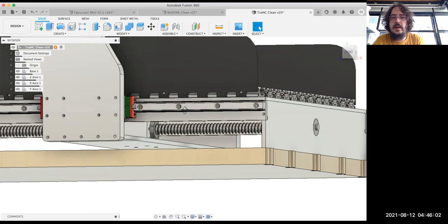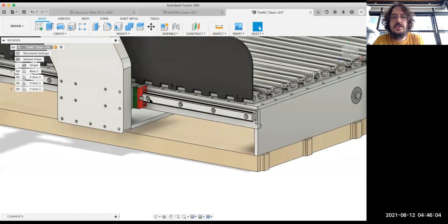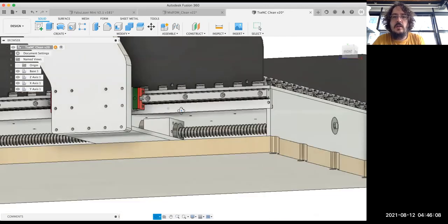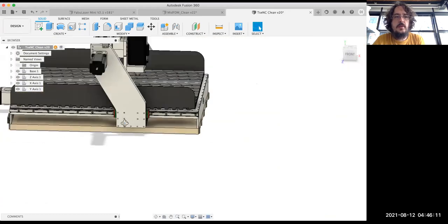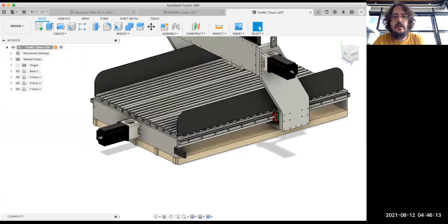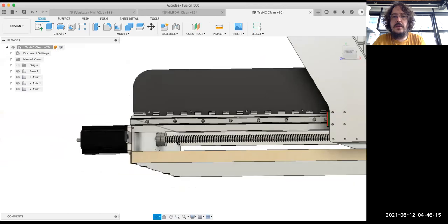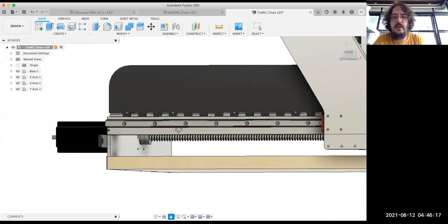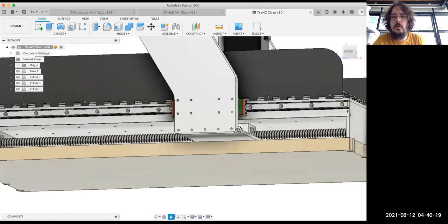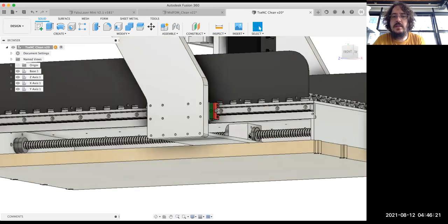And then we use again G15 high wheel linear guides to drive the motion. The machine uses NEMA 24 motors over here with a coupler, and then it basically rotates this ball screw to move this system underneath it that then moves the whole y-axis.